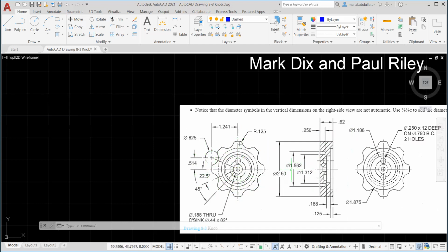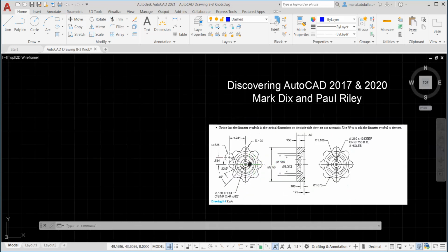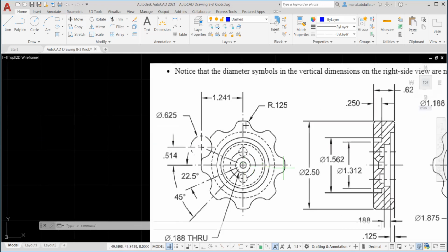In order to complete that part correctly, we need some construction lines. Okay, so let's have a look at that here. The construction lines, we have two kinds. The first one, we have dashed lines. And we have some hidden lines. We need to distinguish between these. So the dashed lines are construction lines, and the hidden ones are part of the drawing that we cannot see, and this is some part of the section as well that we need to track. So we'll use these two kinds of lines, the hidden and the dashed.